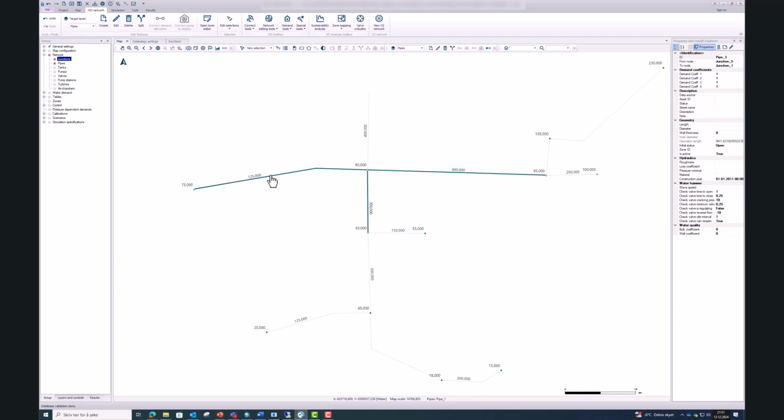The same thing when we are going to put in information. We see the diameter here in millimeters. So I identify it, I click on the diameter field and I press 125. And another input parameter that is important is the roughness. So I'm just going to stick with 5 for now. It's a little bit conservative maybe, but it's a starting point. So we're just going to stick with 5 for our uncalibrated model.